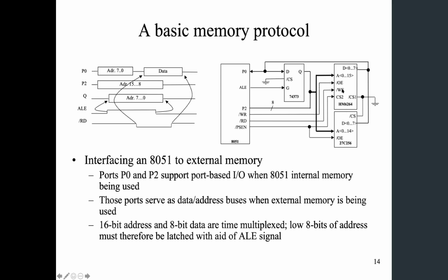When you access these memory chips, for the case of the ROM, it's read-only. So you provide the address, and you expect to get data out. So we have 8-bit data out, and these 8 data bits will be read to the microcontroller to do some computation. And for this RAM chip, you can both read and write. So depending on the operation, you might read data from memory to the processor, or write data from the processor to the memory. Either way, you need to use these addresses.